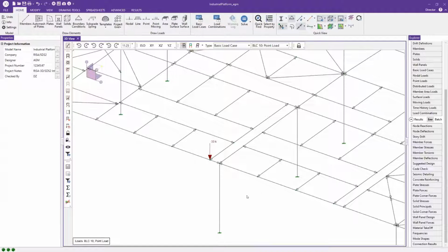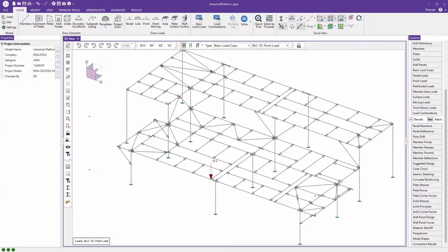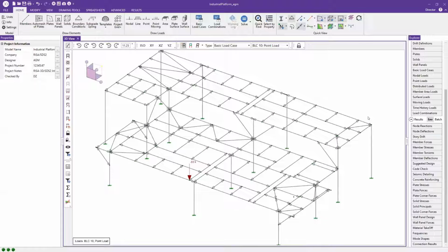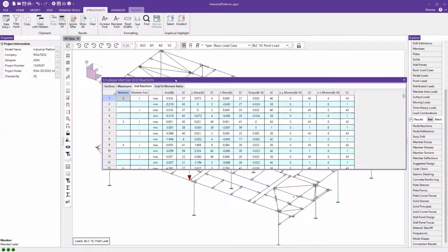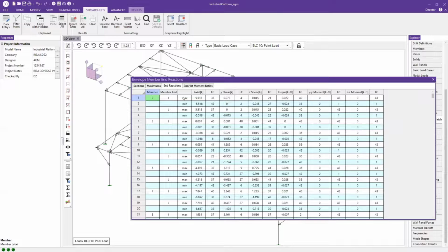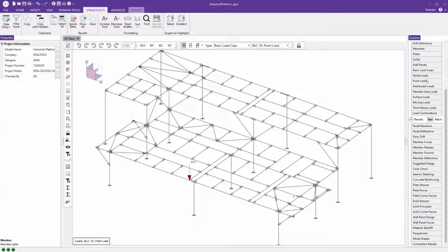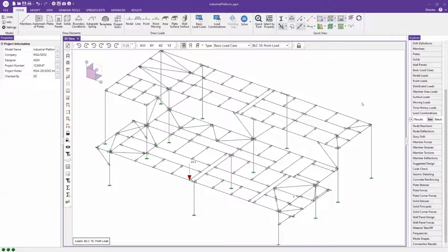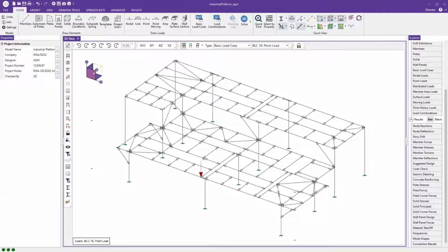All right, so I'm just about done with this model and ready to hand it off to David. The last thing that I'm looking for is these envelope member end reactions. Every member in this system has all of their minimum and maximum end reactions for all 6 degrees of freedom in this big old table. And this is basically what I need to do to get my design over into SDS2. Pretty simple at this point.